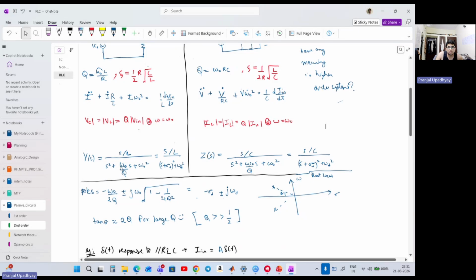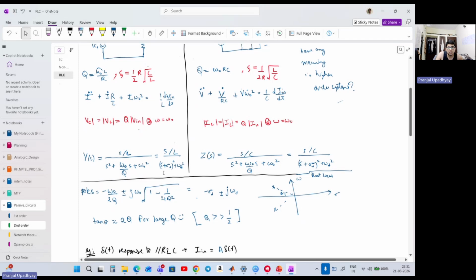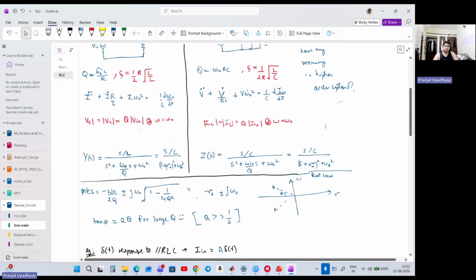Yeah, and again, why this expression is good, especially the characteristic equation of this function, is that it works for an RLC circuit in both cases. Why I'm saying so is because these terms are not containing any specific R, L, or C terms, right? Because if R, L, C terms had been present, then there would have been some difference, because here it is RL, here it's RC. So this is a more general way of expressing the characteristic equation of an RLC circuit. Now we can equivalently express it as this. Now we'll understand how this representation came about. We'll understand it soon enough.